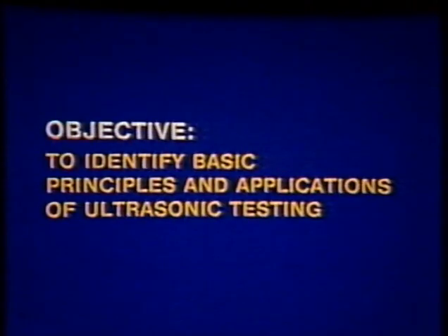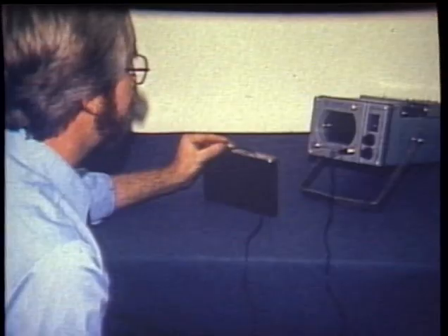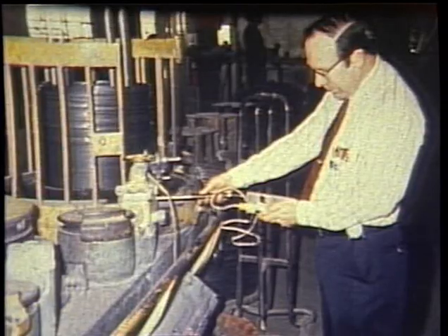The objective of this topic is to be able to identify the basic principles and applications of ultrasonic testing. Ultrasonic testing is a highly sensitive method used for detecting discontinuities found in welds and various other materials. It is used extensively in the welding industry for critical applications where quality is of utmost importance.